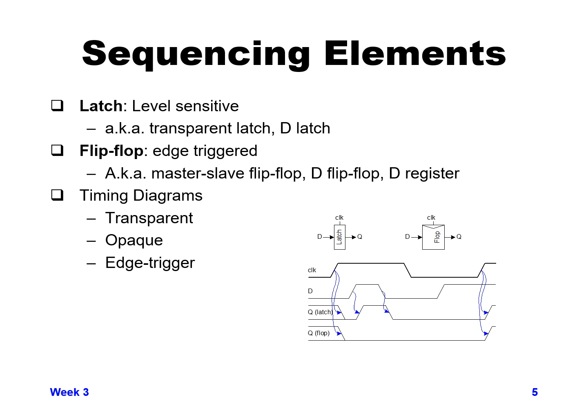So the latch value goes low to match D. The flop on clock switching from low to high also switches, it captures the value of D and says, oh, D is a 0, so I'm going to go from high to low and capture a 0 value.